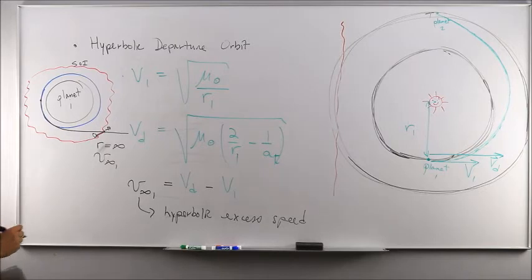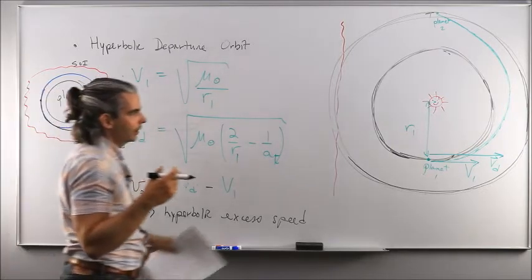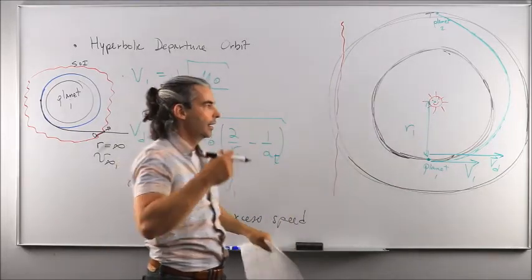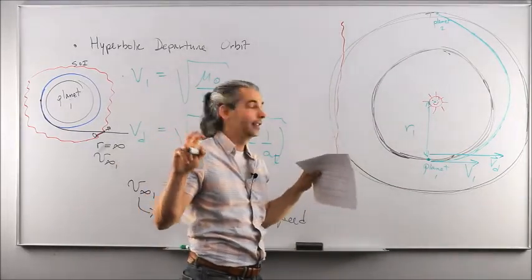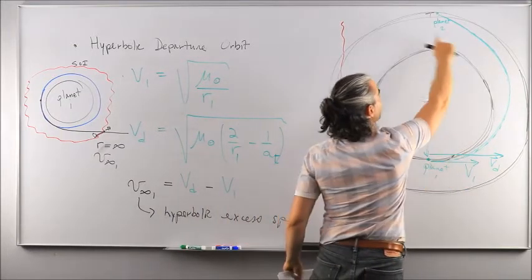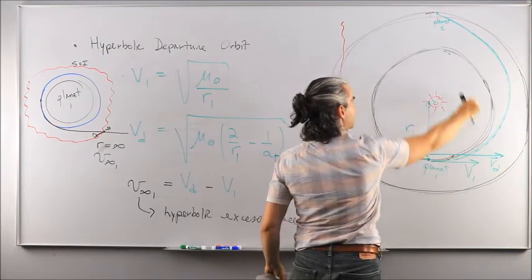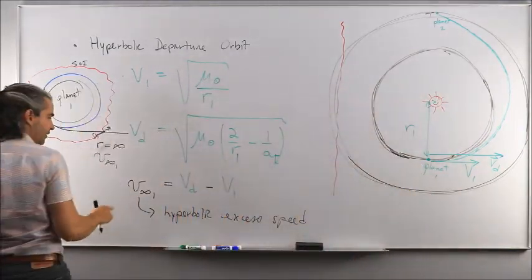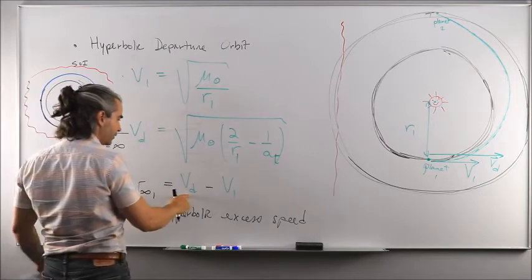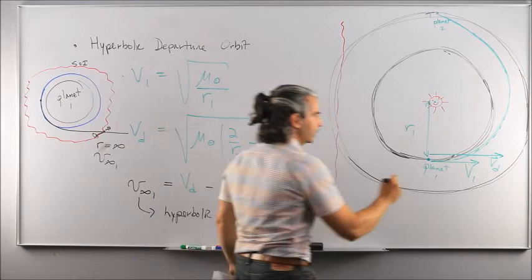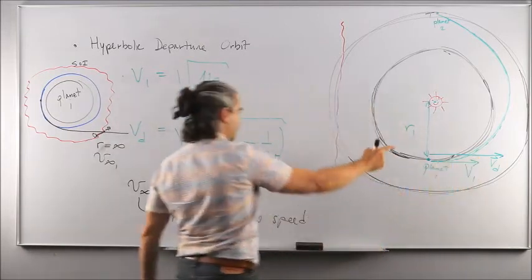Okay? So essentially think of it as doing a regular Hohmann transfer from the heliocentric perspective and finding what I call a fake delta V, which is the difference in speed between the speed along the ellipse at its perigee and the speed along the circle here, and that is your V infinity. So this is almost like a fake delta V, and why I call it fake is because there's no delta V maneuver applied here, right?